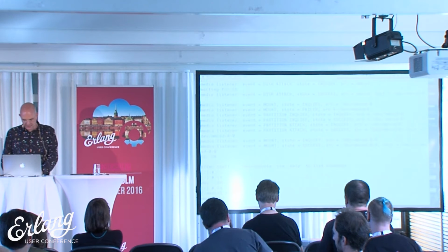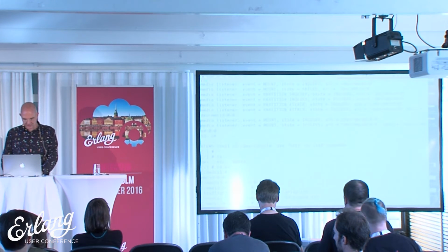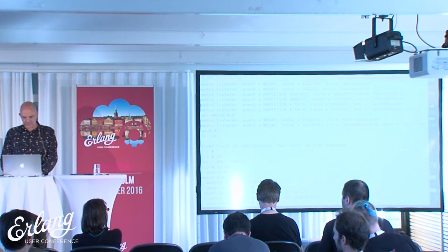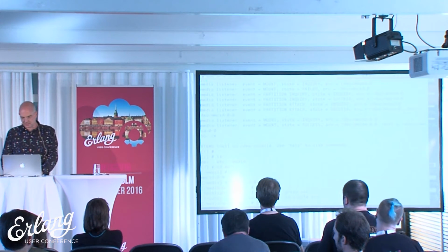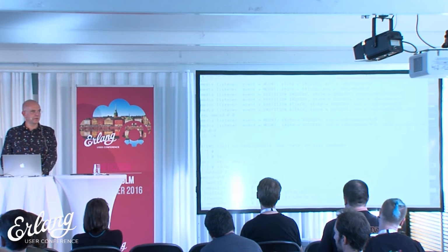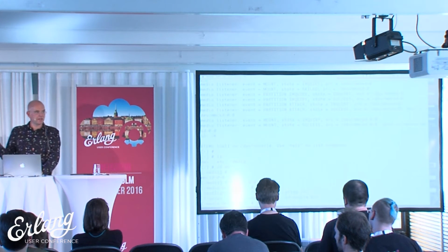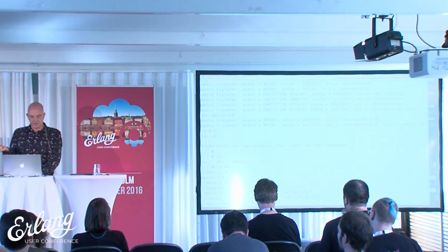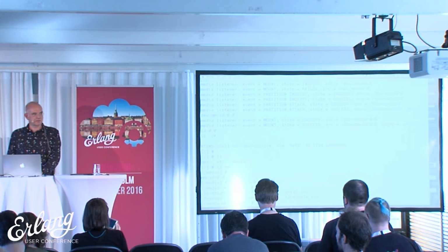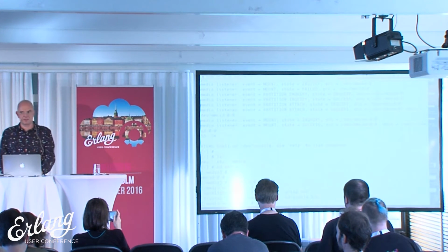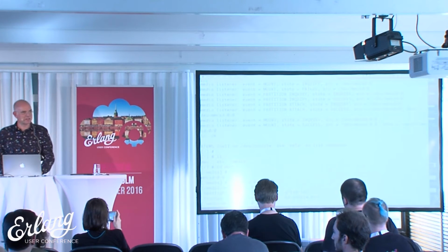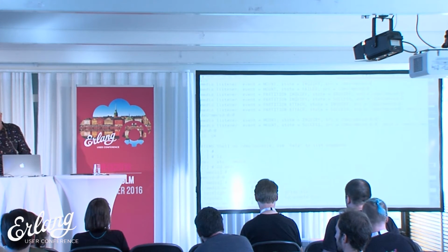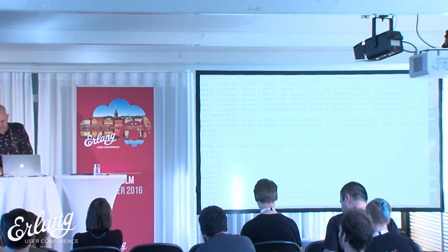So that's the SD card driver, mmcsd-0-0. And if I ls here, you can see an ini file where you configure it, and the .bin file is the actual image that gets booted. That would be your Erlang VM. And then beside your Erlang VM, you just put a release, and then it boots the release. And the other files are some junk my Mac put on it when I mounted it. They tend to leave traces on the Macs. Okay, so let's connect it back.